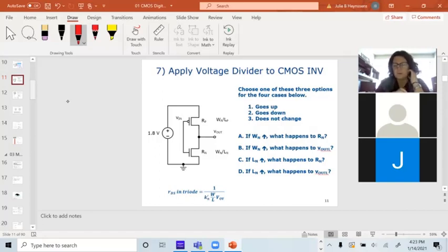When a transistor is on and it's in digital mode, it's in triode. And you can dig this equation out of the book if you're extremely patient, because it's hard to find where they explicitly say it. But the RDS in triode basically equals the transconductance parameter of the process, which we don't have any control over once we pick the process, times W over L, times V overdrive.